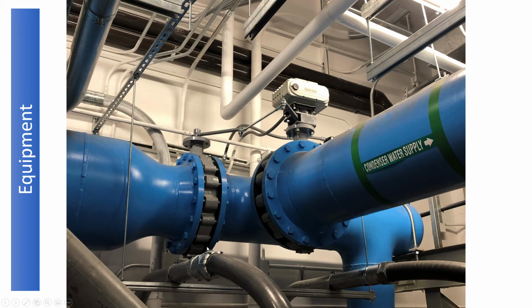But again, you probably know there's a valve inside here and there's a valve inside this flanged disc, and it's being actuated by this actuator that's getting a signal. You can see the electric signal from the building automation system. And it's saying this line should be closed and this line should be open. And what we're looking at here is condenser water. This one goes to the chiller, just like the circuit that we've talked about. Cooling tower water, condenser water goes to the chiller.